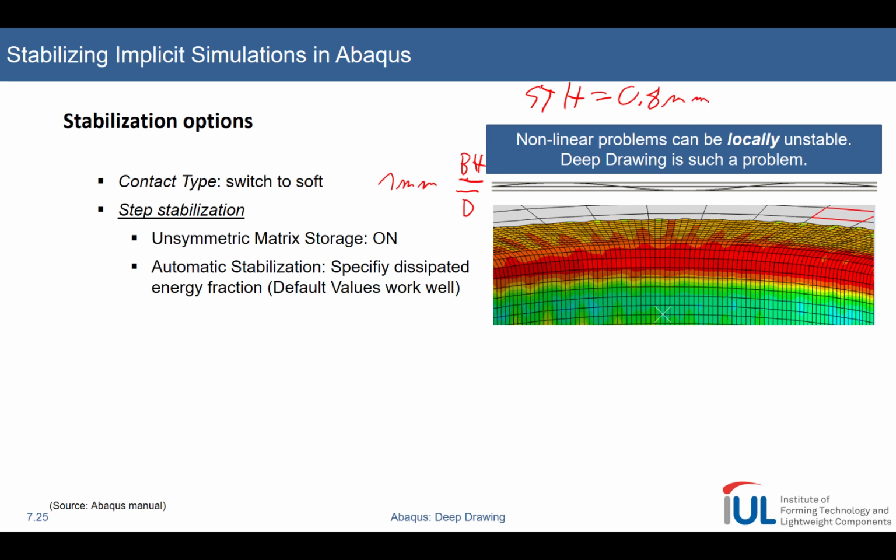So from the very beginning, at the top, between the blank holder and the sheet, and between the sheet and the die, there's 0.1 millimeter free vacuum. So this space will cause, and you should hopefully remember this from your forming technology courses, some sort of wrinkling in your flange. You can see this waviness pretty nicely in this picture, and I've shown this waviness again in the picture here on top.